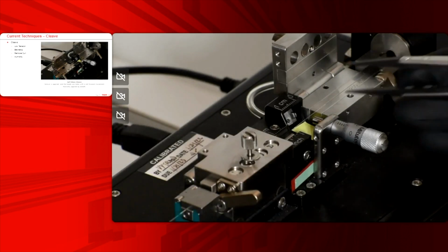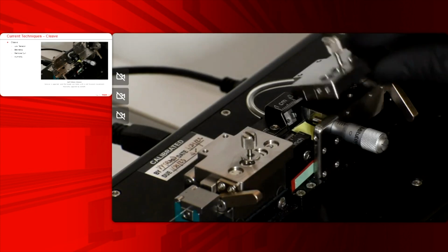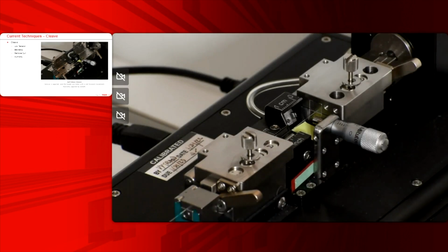You see on the left, I just clamped the fiber, and on the right, I'm lifting the stripped end out and allowing the vacuum to draw it back in, and then closing the lid and engaging the cam. The blade just moved forward there, so it's going to take several pecks, and in a moment I'm going to exhale onto the fiber to just introduce that humidity.